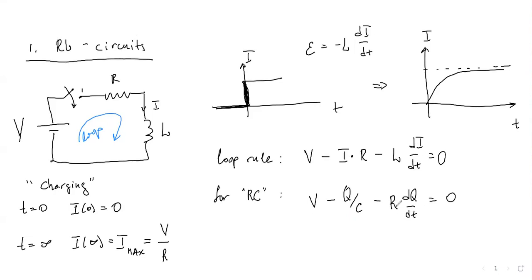So we can take the solution for RC circuits and we can replace the parameters. So for example, I should take capacitance and replace this with 1 over resistance, just if I want to compare the coefficient. And I should take resistance and change it with inductance.